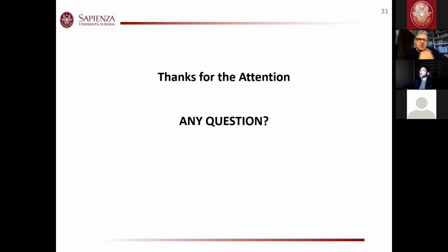One more question is about the Nurbs versus the Polymesh. Do you need to start with Nurbs and then transform it to Polymesh, or can you start off right away with Polymesh? I can start with Polymesh. I did the Nurbs and then Polymesh to show how you can convert Nurbs to Polymesh. But if you set Nurbs into the loft command, you can create Polymesh.